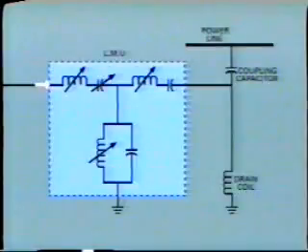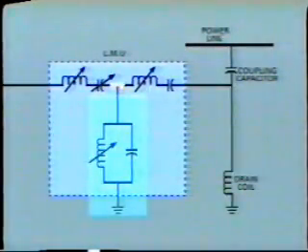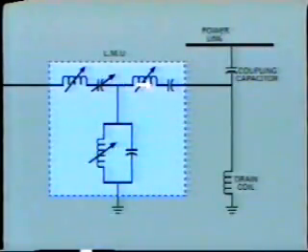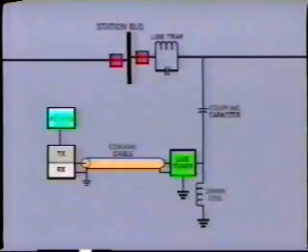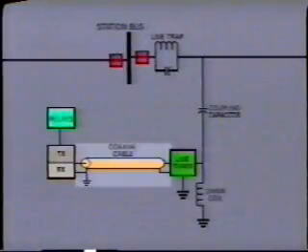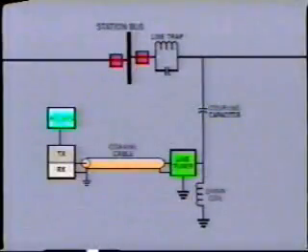The incoming signal passes through a variable inductor in series with a variable capacitance, and then passes through a shunt connection to ground through a parallel resonant circuit. Finally, it goes through another series resonant circuit before the signal connects into the coupling capacitor. The signal input from the carrier is via a grounded coaxial cable, which we have shown grounded at both ends. Some utilities ground only one end. Check your utility's procedure.